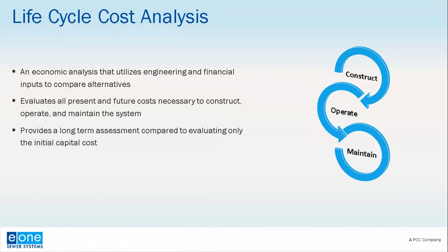So typically we're going to look at gravity, vacuum, and low pressure sewer. And this is a non-biased, black and white view of what the costs are going to be based on local conditions and details. It evaluates all present and future costs necessary to construct, operate, and maintain systems, and it provides a long-term assessment compared to evaluating only the initial capital costs.